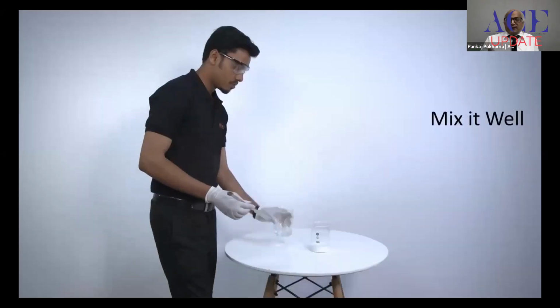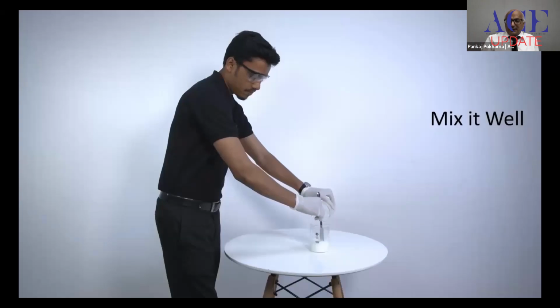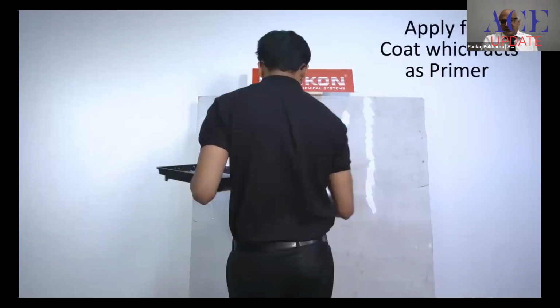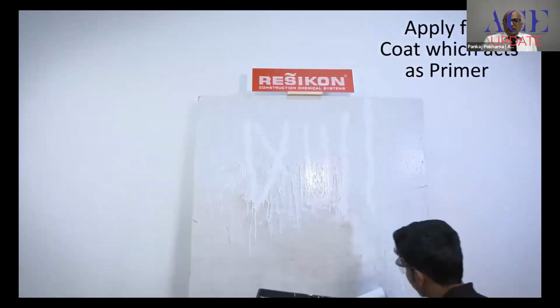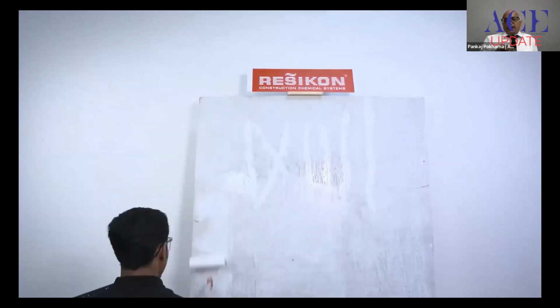This has to be applied in 3 coats. The first coat has to be diluted with water at 50%, means 1 kg chemical, then half kg water. On this treated surface, you have to apply a primer coat. The primer coat will have a penetration as well as dust binding property and act as a bond coat for the top 2 coats to come.